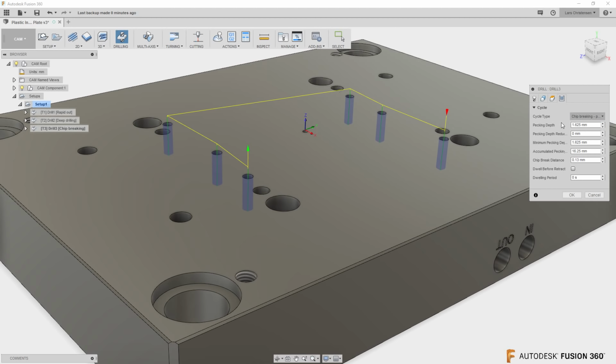So the first distance, I mean, if you could go the diameter, and then down here you set how much it's going to lift up the tool. What maybe is like 0.5mm or something like that. It just pulses up as it's drilling down.